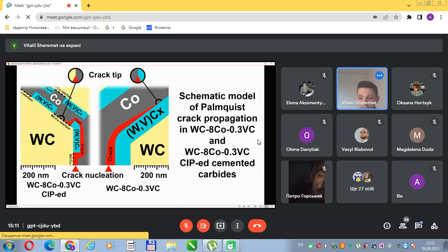As reported in a recent study, and which is consistent with the data obtained in this work, cold isostatically pressed samples have thinner tungsten carbide grain size compared to those that did not undergo cold isostatic pressing. This implies that the specific surface area of tungsten carbide grains in cold isostatically pressed specimens is increased.